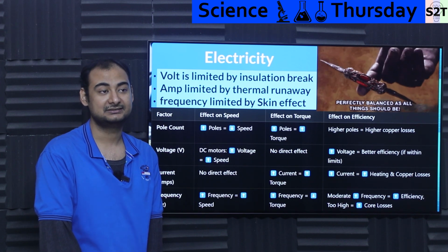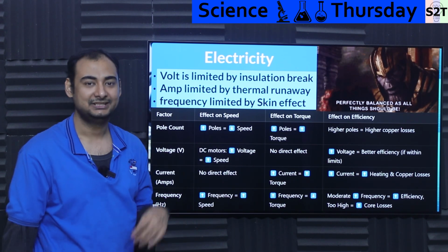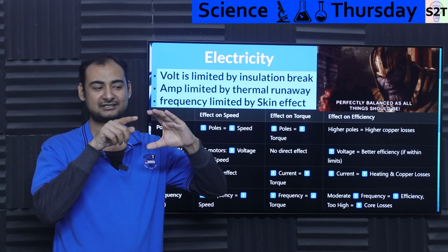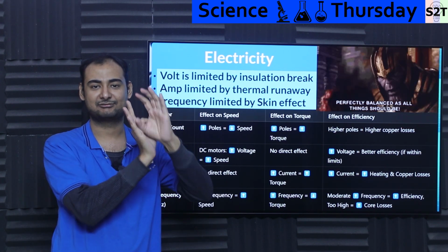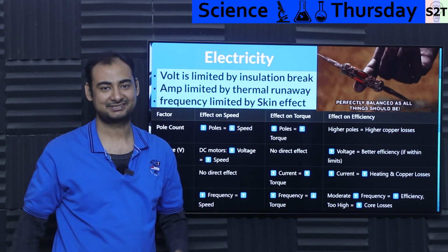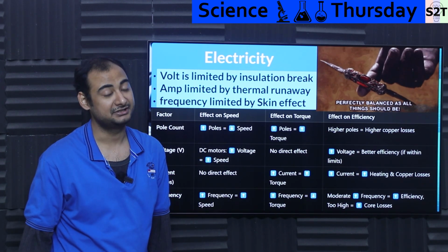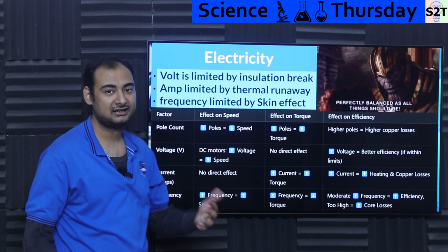You can. It's just that there is another penalty known as skin effect. You will reach a point where even though you can have a giant thick conductor, the conductor is like, no bro, I'm not this thick, I'm this thin. Why? Only the skin is utilized, the core is wasted because of the high switching frequency. So skin effect is the upper limit there.